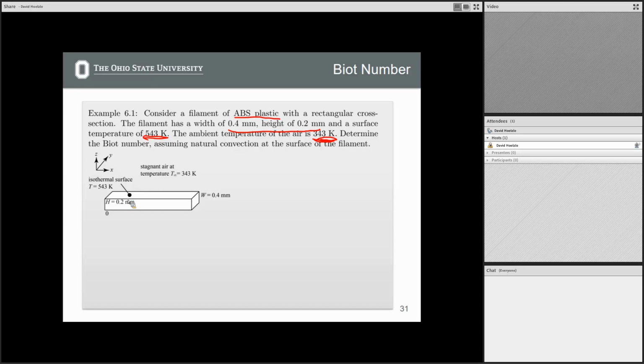So if you really want to apply this to any type of problem, you have to get into a heat transfer textbook and go through what your geometry is, what type of convection you are working with, all these factors. This is the case of going through this for natural convection on a flat plate. If this plate was at a slight angle, we would use completely different equations based off the relationships people have derived before.